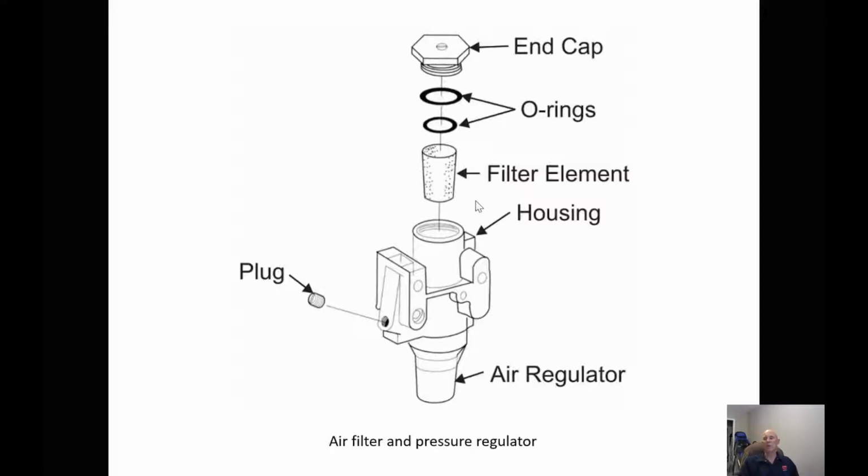So one of the symptoms might be an operator comes to you and says, yeah, it's shifting really slow. Now again, some of the O-rings that we use aren't compatible with oil, so the O-rings could start to swell and that could cause some of the pistons to slow down. It could be that the regulator isn't delivering the amount of pressure we need.